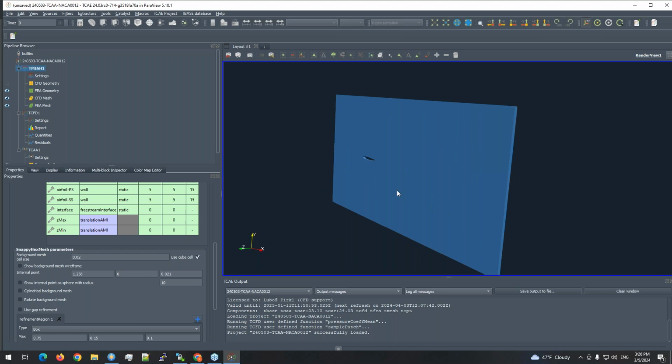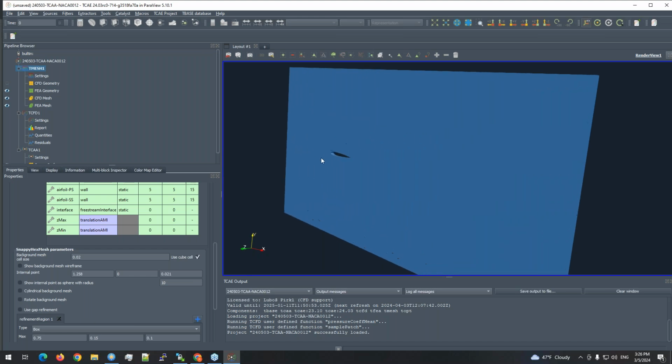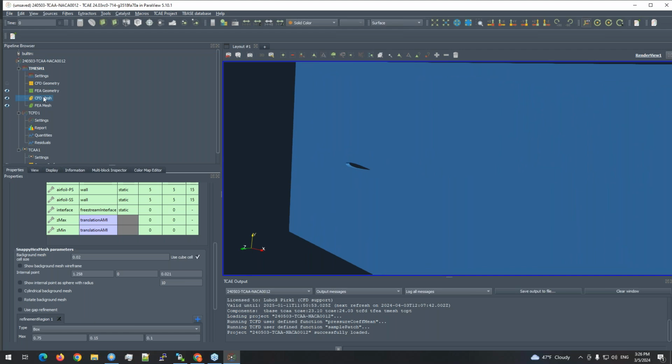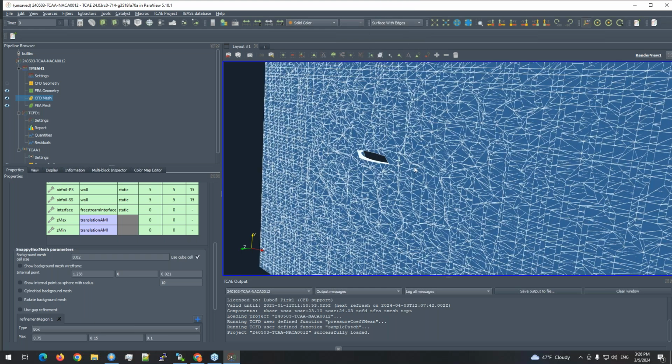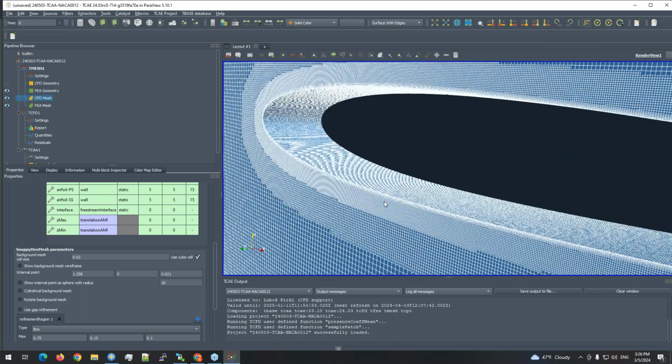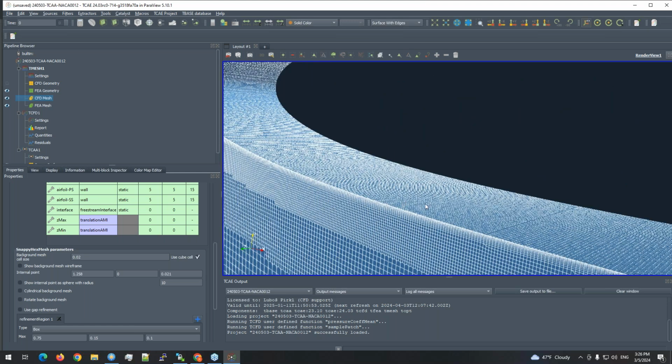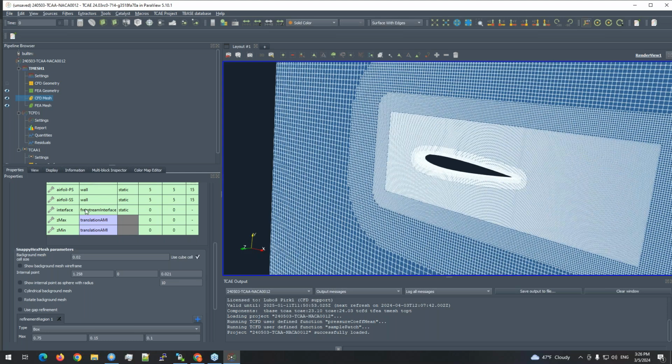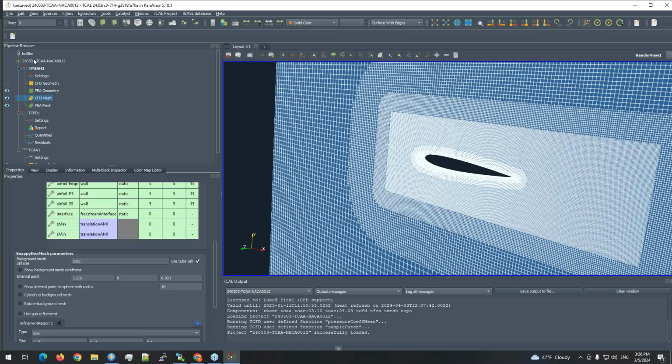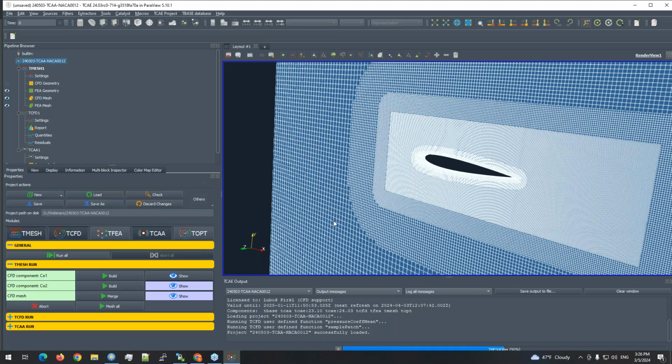Okay, thanks. And the resulting mesh then looks like this. We can visualize it here in the CFD mesh item. If we look at the final mesh, we have a very fine, nice mesh with a high inflation layer size, and this is the resulting mesh together with the external one, joined together and used as a simulation domain on a simulation mesh.